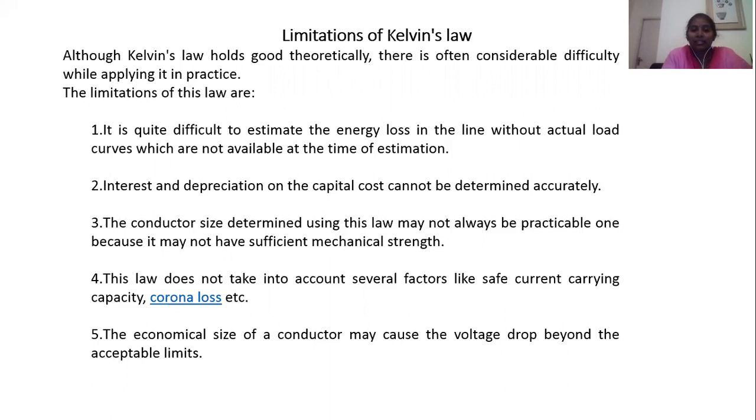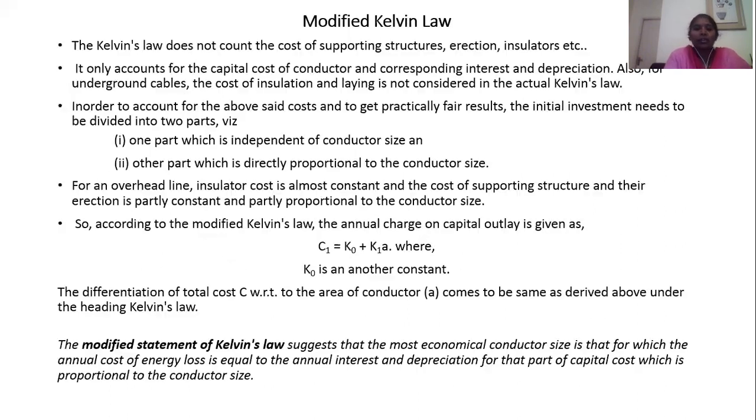Another thing is that the conductor size determined using Kelvin's law may not be practically applicable, because it will have insufficient mechanical strength. It will not be mechanically robust. This law does not take into account several factors like the current carrying capacity, corona losses, etc. Also, the economical size of the conductor may cause the voltage drop to go beyond the acceptable level.